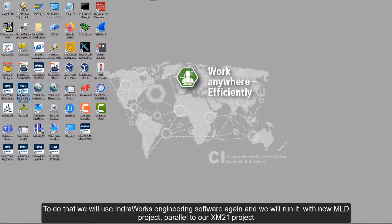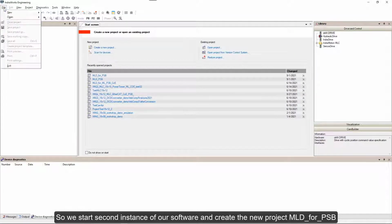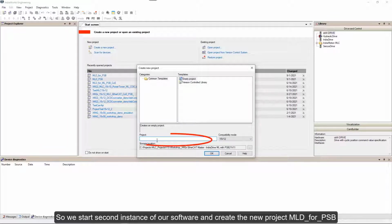To do that, we'll use IndraWorks engineering software again, and we'll run it with new MLD project parallel to our XM2x project. So we start second instance of our software and create the new project, MLD for PSB.